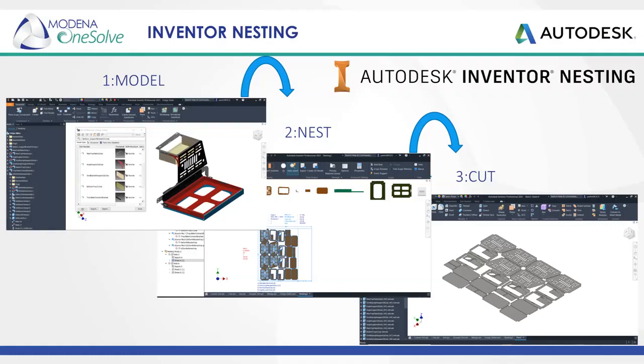The second phase is where the Inventor nesting comes into play. How this works is Inventor nesting will extract the shape profiles and flat patterns from your model. The required shapes are then analyzed by the program's nesting algorithm. This will automatically arrange, nest, and organize your shapes on a single sheet or across multiple sheets. Inventor nesting is intelligent enough to automatically match all the different part materials and thicknesses being used, and then align them onto the corresponding sheet.